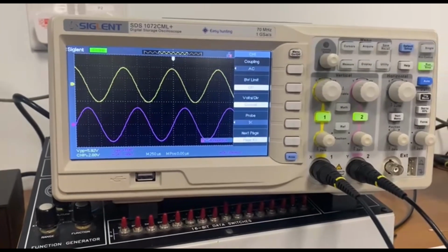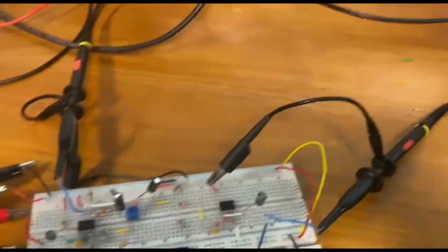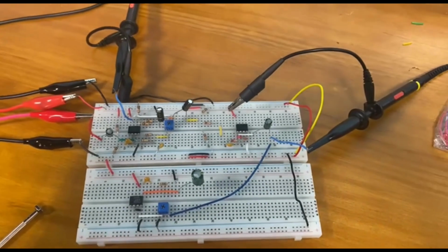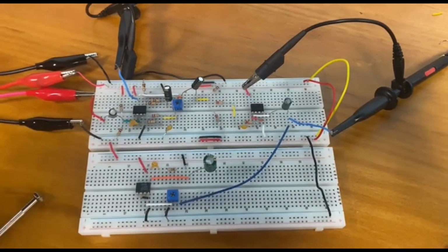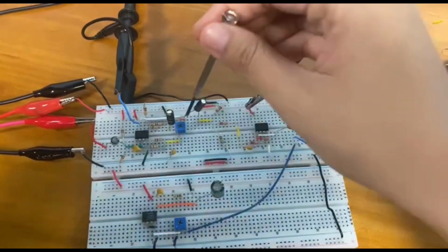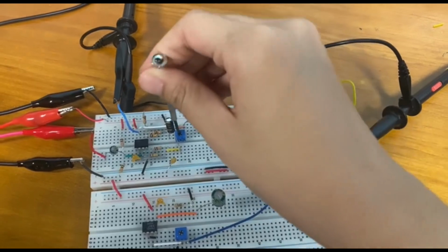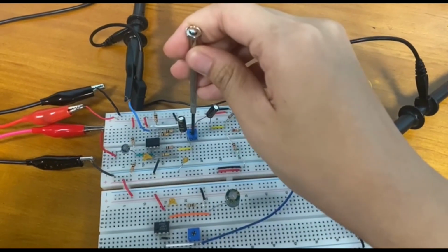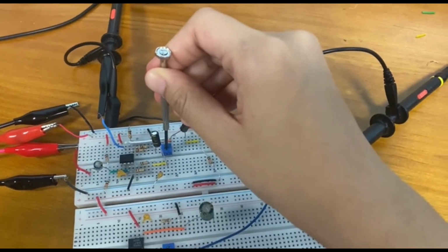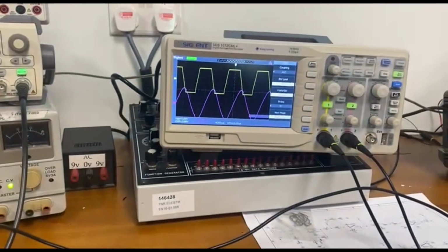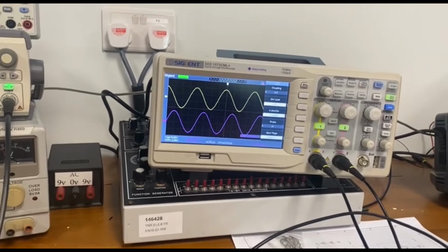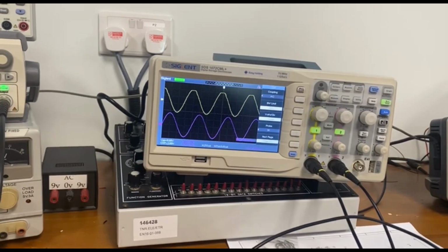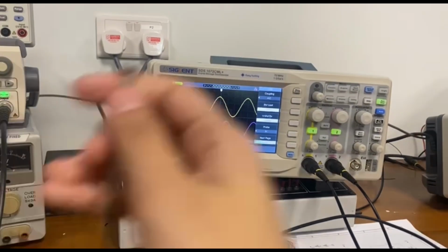For stage 3, channel 1 is connected to IC1 pin 7 and channel 2 to IC2 pin 1. As I turn the trimmer, both channels become flat. Trimmer P1 controls the gain or offset voltage, ensuring a clear and precise heartbeat signal for further processing. Adjusting TP3 affects the output waveform at TP4. At 100 Hz, the waveform is amplified at unity gain.